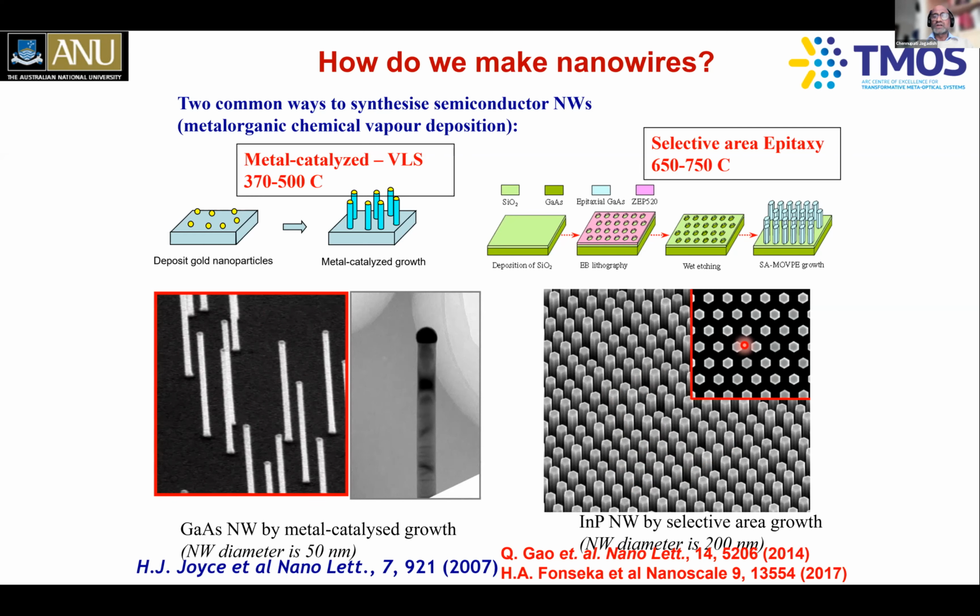You can see beautiful hexagonal facets because these nanowires are growing along the 111 crystallographic orientation, because we're using 111 crystallographic orientation substrates, because that's the lowest surface energy orientation. That's why these crystals like to go in that particular crystallographic orientation. This is the work of my former student, Dr. Chian Gao, who is now a research engineer at Blue Glass, a company which is trying to make LED glass substrates, for example. Again, we made nanowires as small as 70 nanometers using this technique and as big as 700 nanometers. And again, depending on the applications, you choose the right diameter of the nanowire.